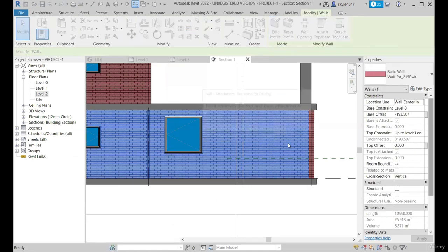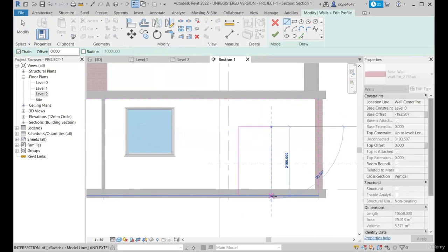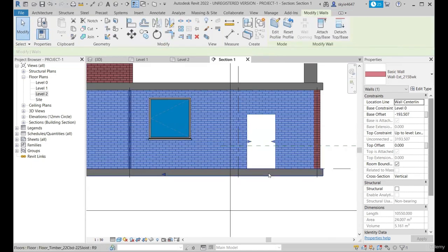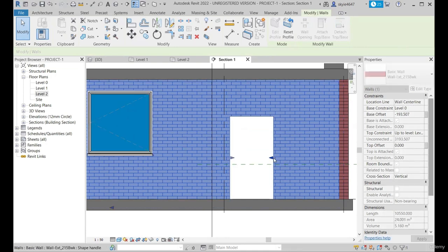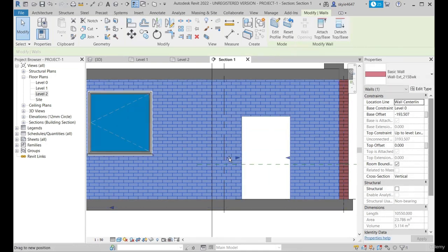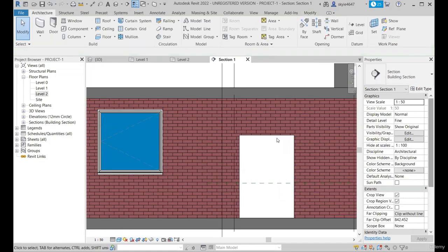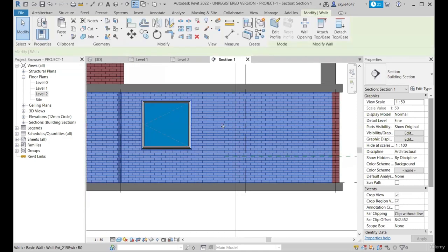Another way of creating an opening here is by using edit profile. Go to edit profile, and you can simply have a diversion here, and split the connectivity of the bottom outline and have it trimmed so that a single loop is formed and there won't be any error. In this way, you can have the wall opening created using edit profile, and you can use the shape handles here to drag or control the width of the opening. Okay, so let's reset it back again.